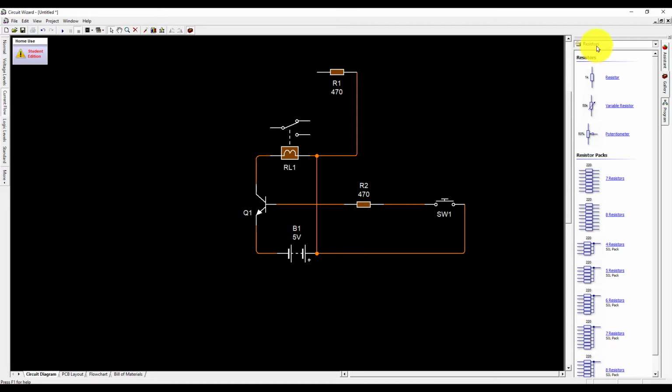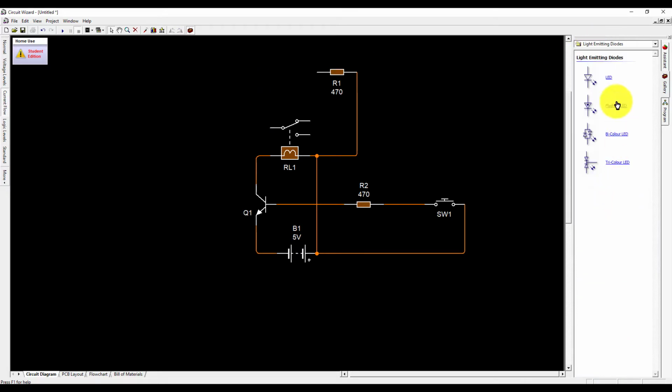So I'll put another LED this way, and let's connect this one here. Draw a wire here. Okay, play this, push this. Yeah, I made a mistake by placing the diode the wrong way. So this is our relay module. This is our signal pin, this is our common, and this is normally open and closed. If you want to test this relay module, this is our application.